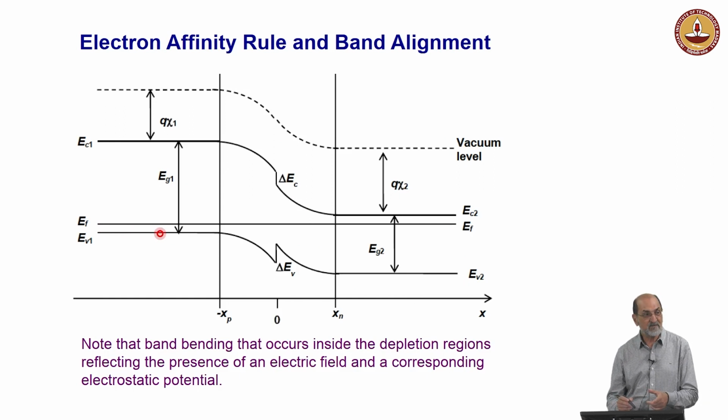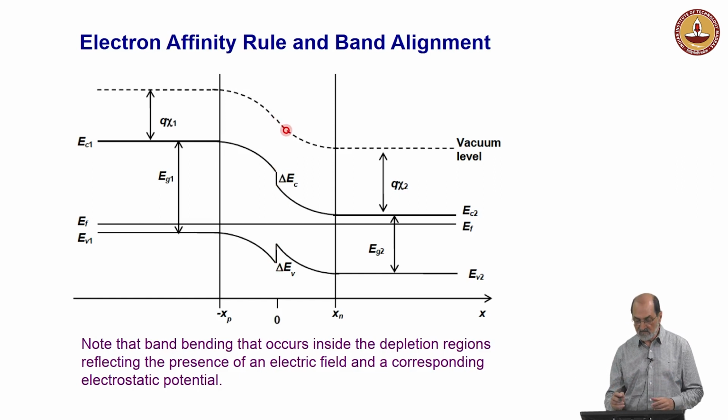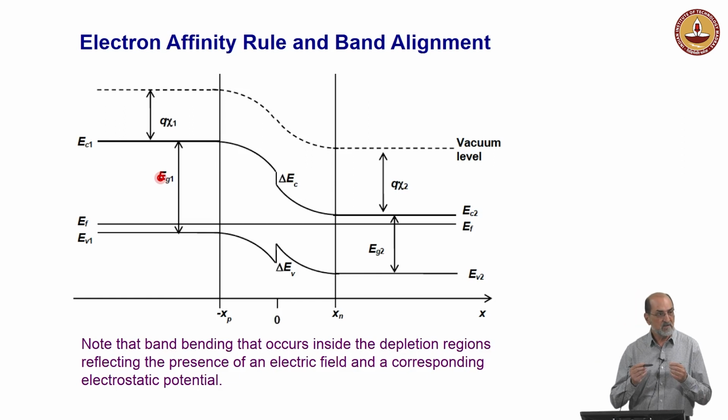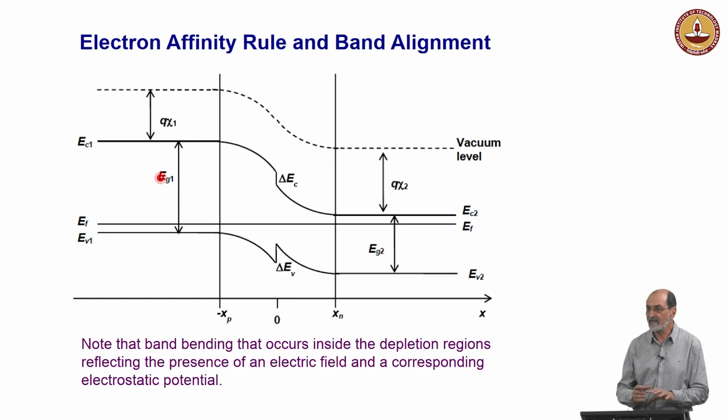But if you draw this in your first step, I can guarantee you are going to be lost. It's very confusing. So first you have to know where these levels are, and then you make the band bending in such a way that you arrive at the bulk with an n-type and a p-type semiconductor. It seems to be simple, but it's very confusing. And it seems to be very confusing for many researchers, because I regularly receive manuscripts from all over the world, and they're wrong. They don't know how to match things, and you can find any kind of thing.